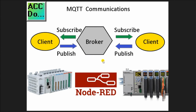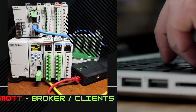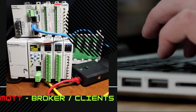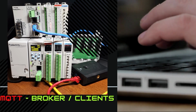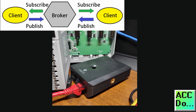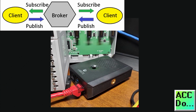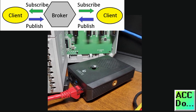Hi everyone, today we're going to be looking at the Productivity PLC Node-RED MQTT. Now we will be using an MQTT broker in Node-RED to communicate to the Productivity PLC clients. MQTT stands for Message Queuing Telemetry Transport. This simple publish and subscribe communication protocol does not take too many resources.